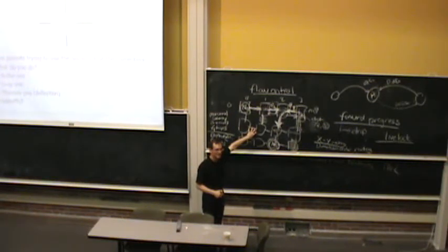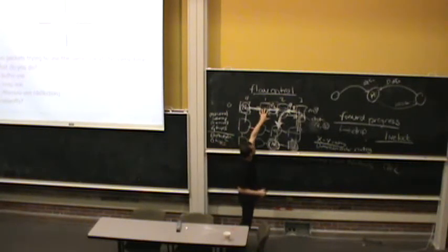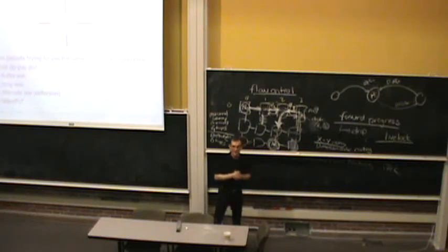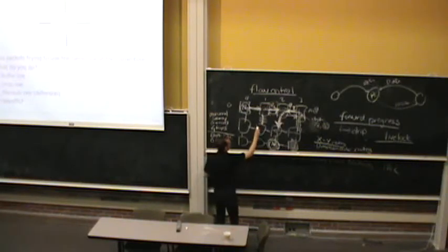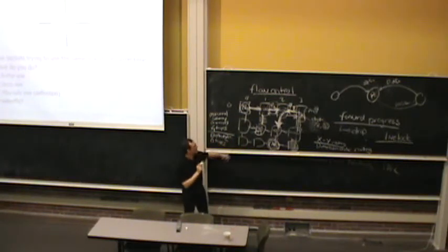also in these mechanisms, dropping and deflection, because contention causes dropping as well as misrouting, and lots of nodes drop and misroute, and lots of nodes are not making fast progress. The advantage of buffering is when the network is really congested, you have lots of traffic, but the traffic is moved into these buffers, and there's smooth movement from these buffers into those links. So you essentially buy bandwidth, have more bandwidth by adding more buffers. This is not present in dropping or deflecting.